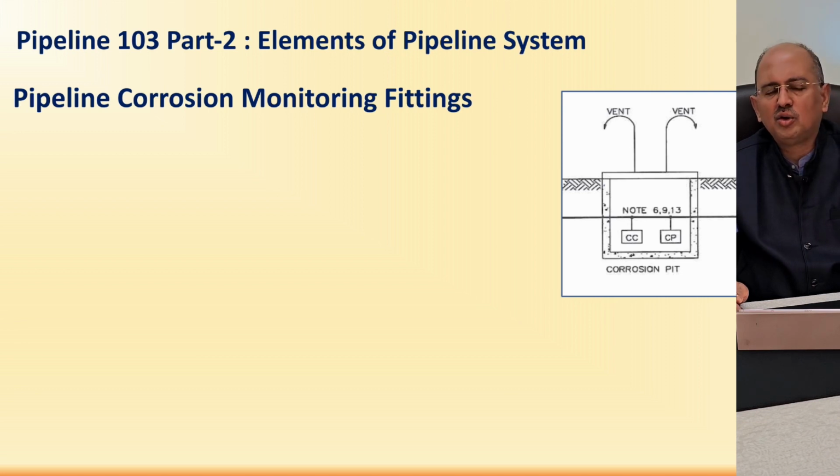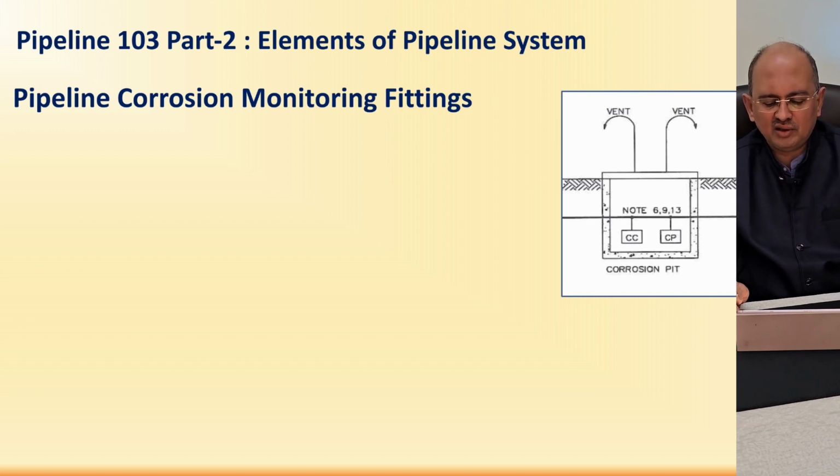Then you should also be able to ideally predict how much corrosion is happening. So for that, corrosion monitoring pits are installed along the pipeline. Normally, they are provided at the start and end of the pipeline, and also at strategic locations at the low points along the pipeline, where there is a possibility of stagnant liquid, which can aggravate the corrosion at such points.